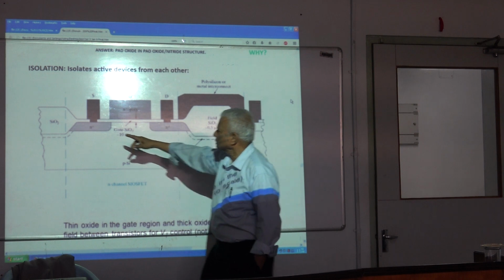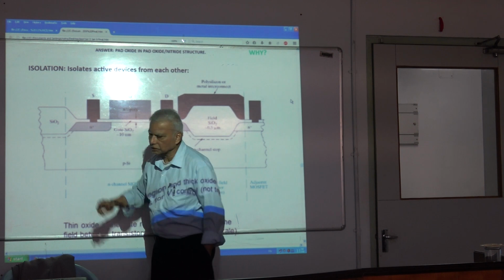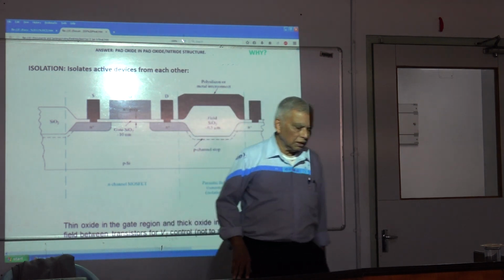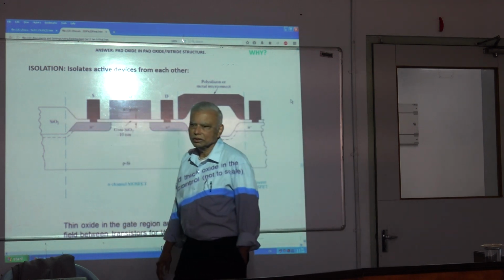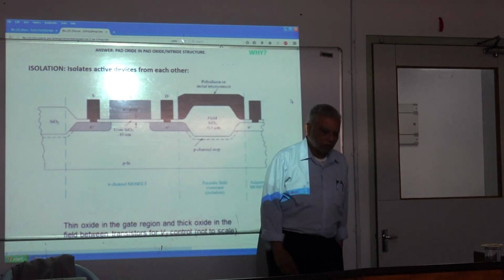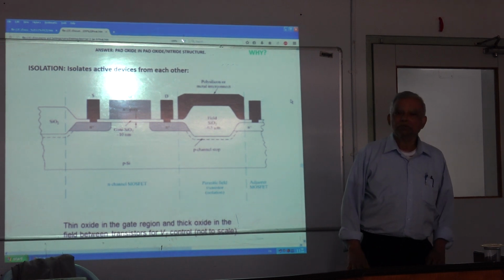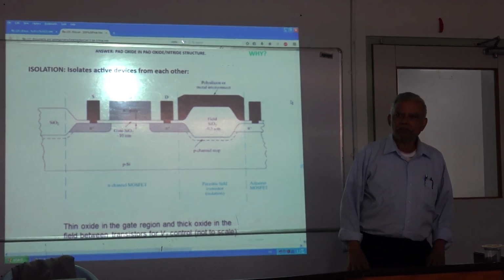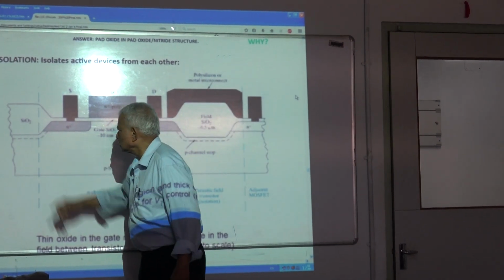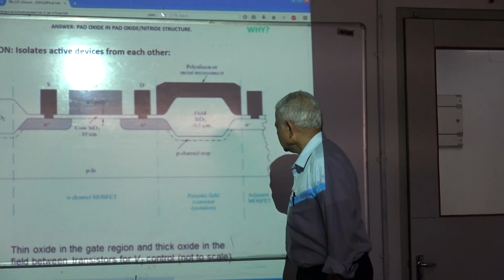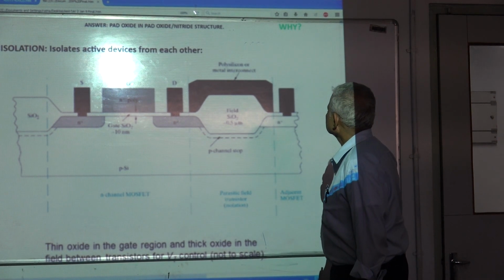The way we used to make this oxide isolation is put a layer of oxide and nitride, and the nitride creates stress right into the oxide. It lifts it outside, and then it creates this wide region which not only creates a problem of reducing the isolation size, but it also creates some defect problem of the dielectric. So we eliminated that. No longer do you see that kind of isolation. It's gone almost 2 decades.